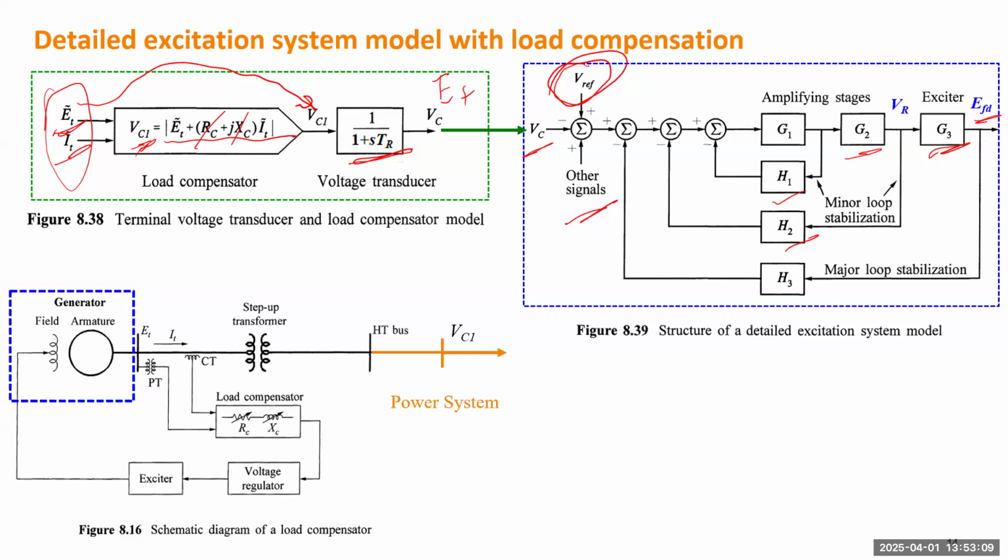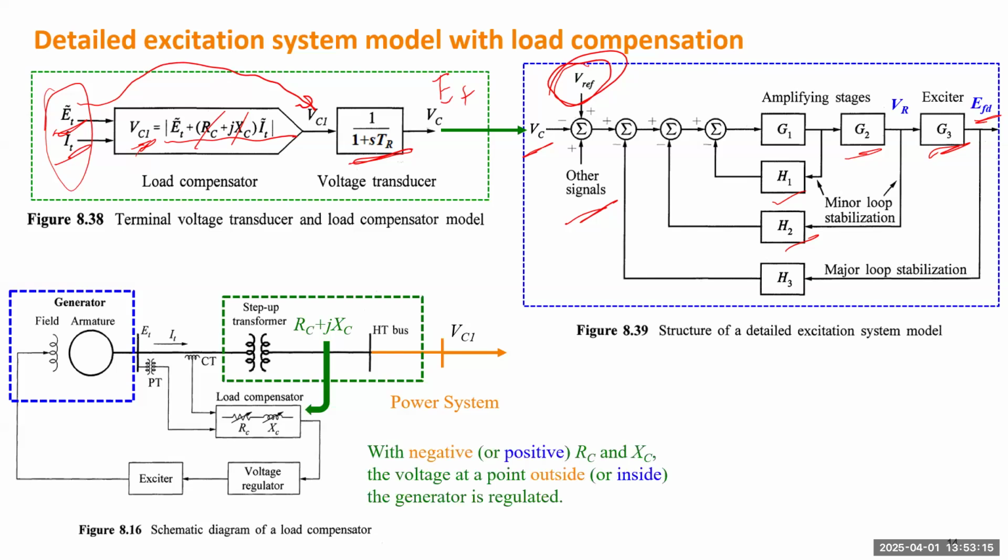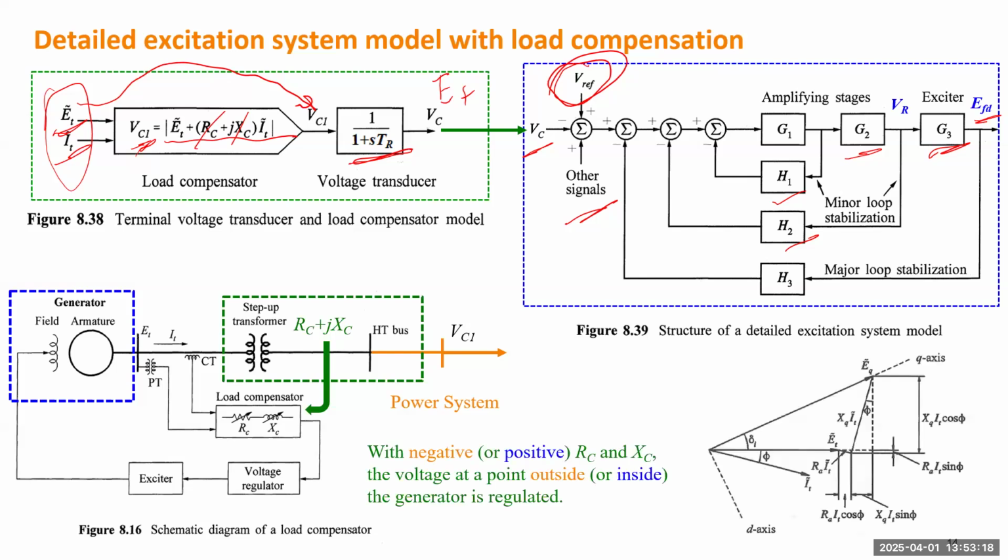Yeah, we can. So this is just detail, but let's talk about the same story. If you don't look at the answer, just use this phasor diagram. This phasor diagram describes how you get terminal voltage from the internal EMF EQ. The EQ is much longer than ET, right? In this case, this is terminal current IT and terminal voltage ET. That's the same IT, ET there.